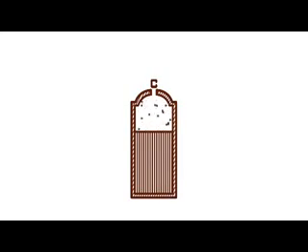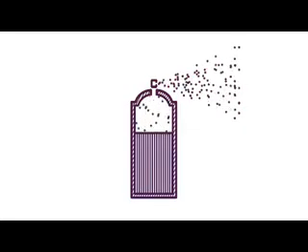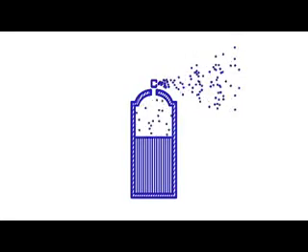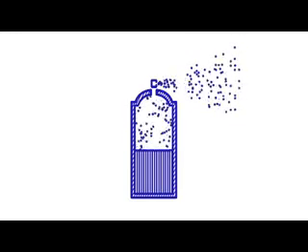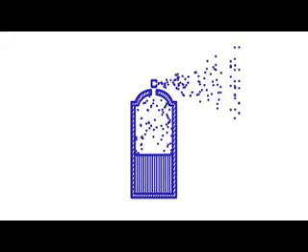You directly experience something like mechanical cooling when operating an aerosol can that, when sprayed, has cooled in your hands. What's happening there is this. By releasing the nozzle, you release some of the pressure inside the can. And we already found that with decreasing pressure comes boiling. The fluid is turning to gas. Boiling requires heat in order to change the liquid into a gas. And your hand feels colder because that can sucks the heat away from your hand to facilitate a state change inside the can itself. The can feels cold.